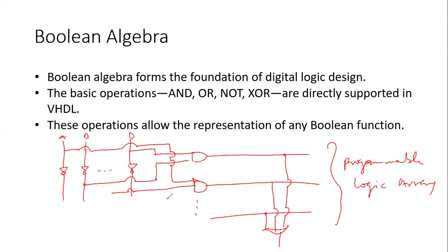The columns for the inputs are drawn, all of these lines for the input. The inverters are included in the adjacent columns like we have here. Then the rows of AND gates for each minterm are drawn, all of these AND gates. Then the OR gate is connected to the minterms in the manner provided. That's more like the flow.